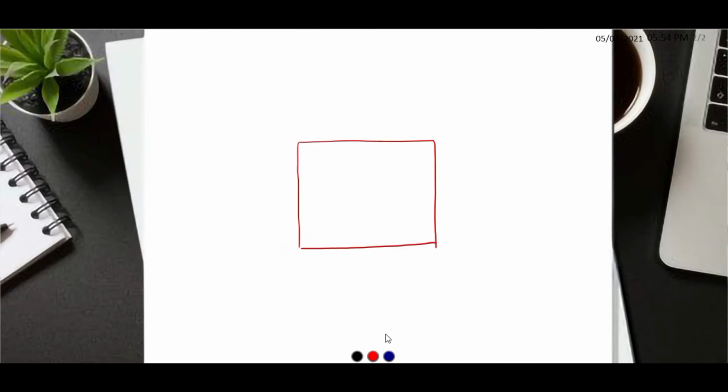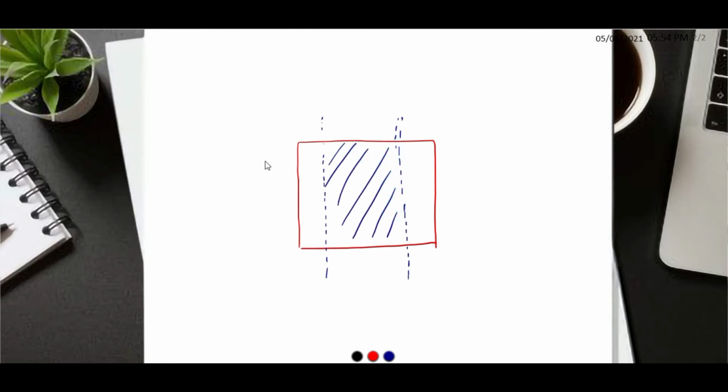If this is our slab and right now we are designing it for, say, the central strip, this one along this direction. Similarly we are designing it for this strip in this direction. So I already told you this is half of the side of the strip. So if this is 30, this will be 15 foot. We have obtained the moment in k feet per feet.